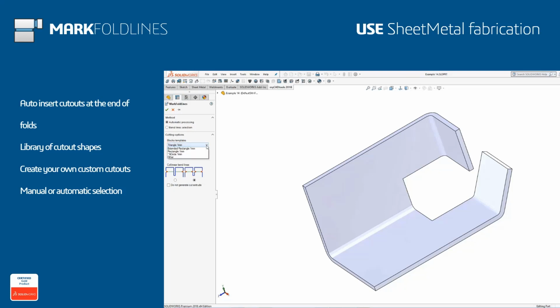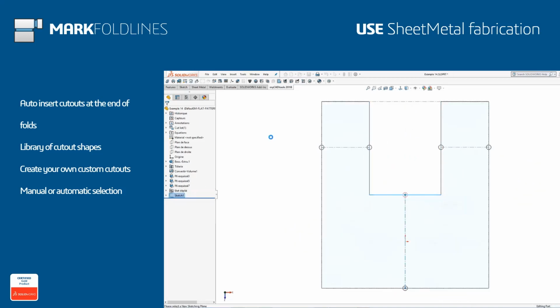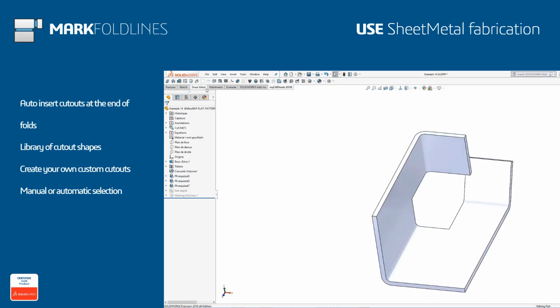Simply launch the tool and select the shape of the mark you want to make from the available options. Custom cutouts can also be added if required. The tool will then process the sheet metal body and remove material as you have specified, marking the fold line to the operator. This takes a commonly manual process and automates it with its own property manager and set of comprehensive options.